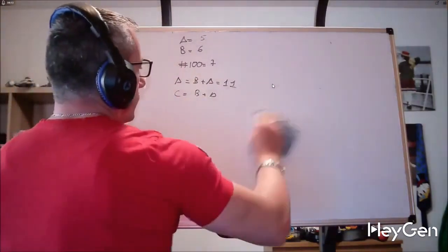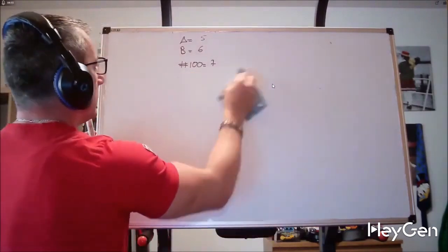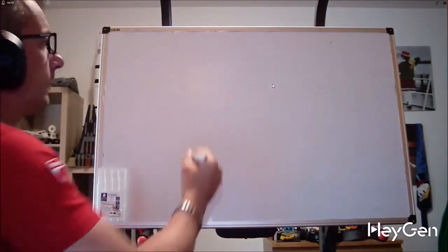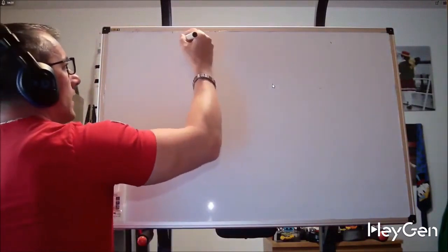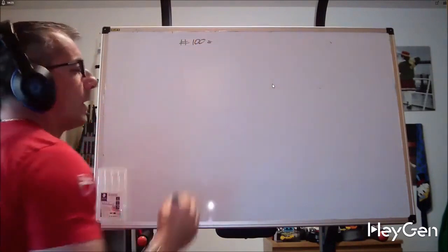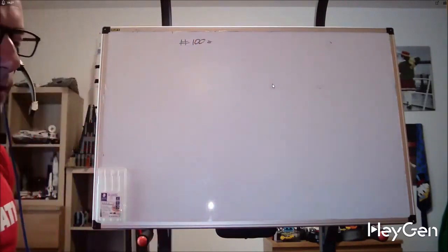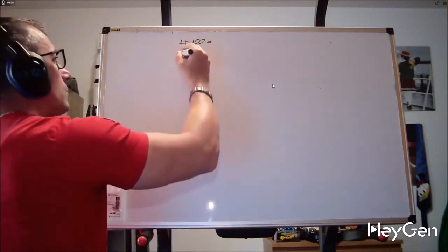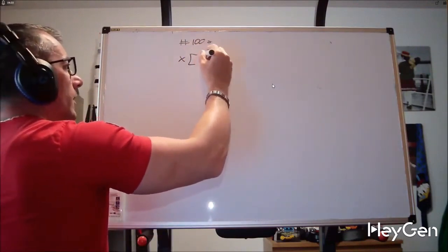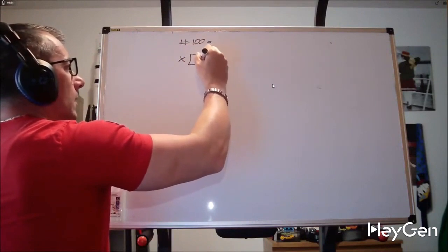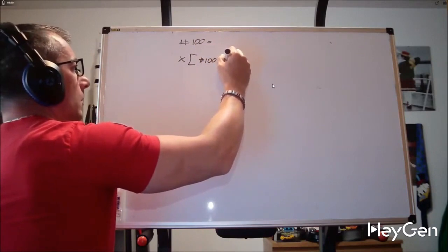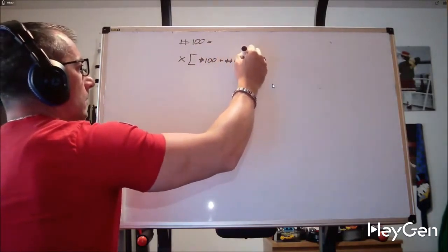So let's open a small parenthesis regarding our simulator, that is FANUC. FANUC identifies, as I told you, the variables with a hashtag, number, equal sign, and if I need to do calculations, x, open square bracket, #100, plus, #101.